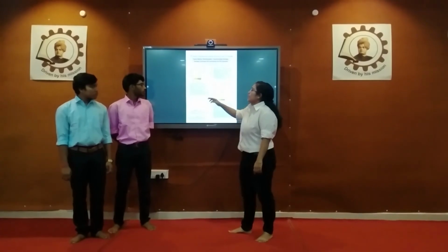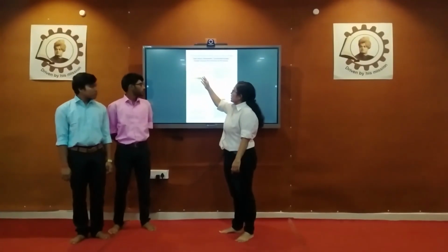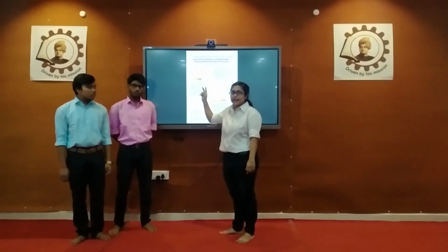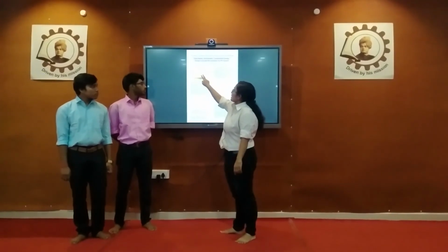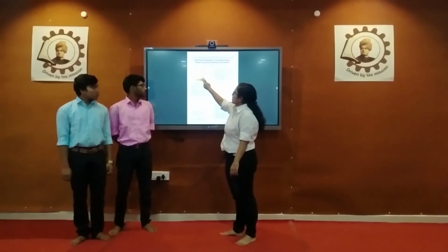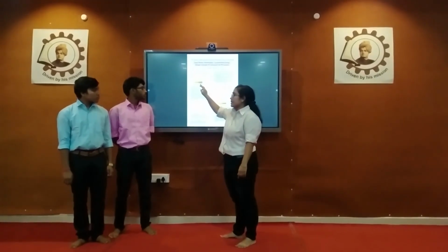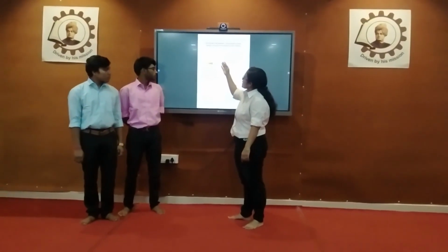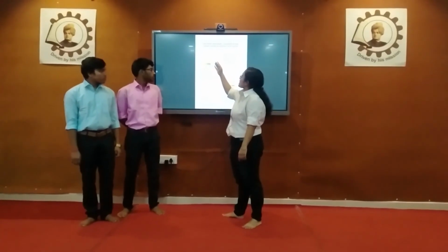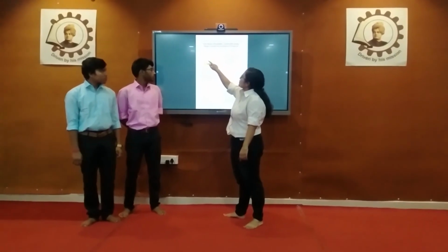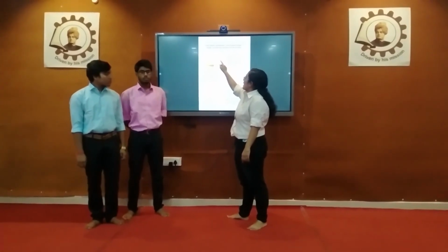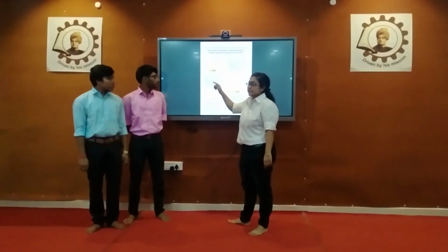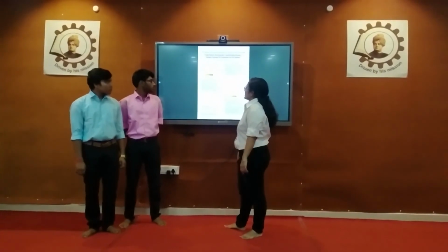the proposed prototype. Our proposed topology is this circuit where we use a total of 2 sources, which are solar panels, and these are 2 DC sources. One is V0 using 1 panel and the other one is V1 which is using 3 panels, and we are using 8 switches. Among them, 4 switches P1, P2, P3 and P4 are polarity generating, and S1, S2, S3 and S4 are level generating. And this is our proposed topology.